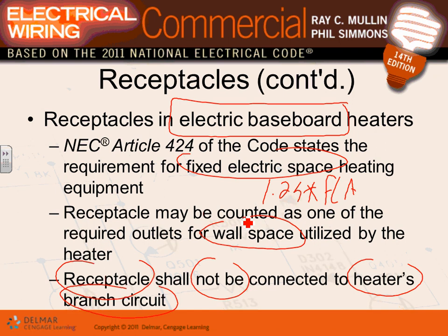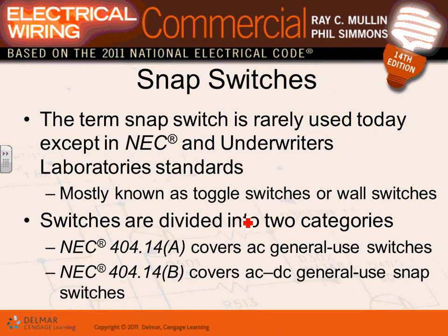What happens, guys, to heat the area? Sometimes they have electrical baseboard heaters. Then you have no room to put a receptacle. So, smarter years ago, they designed a baseboard heater with a receptacle. The only thing you need to pay attention to is that now you're looking at two circuits, one for the heater, one for the receptacle. Any comments, any questions? Matt, does it make sense? Derek? So these are the things that you guys have to know about receptacles.